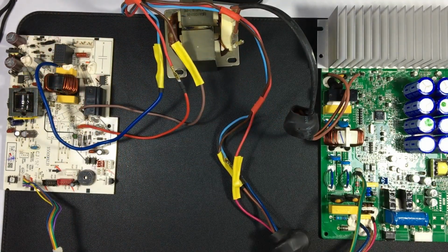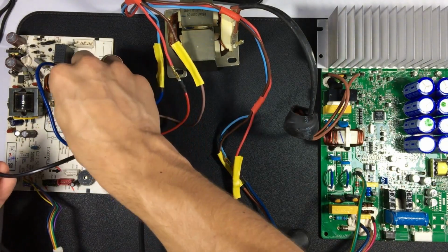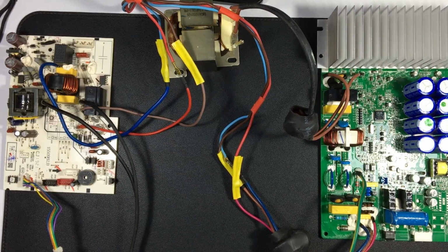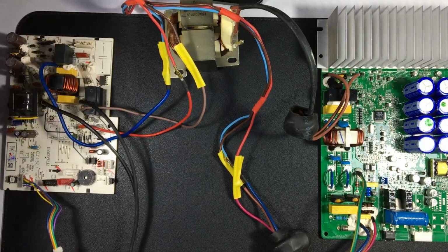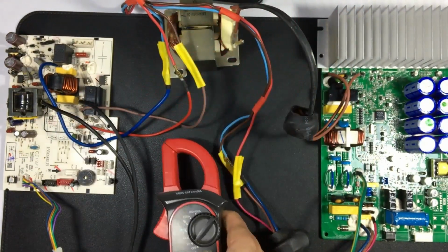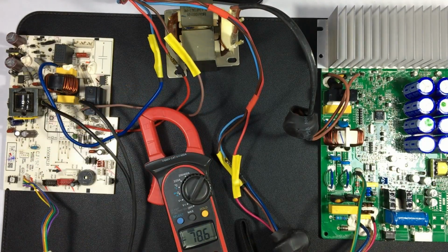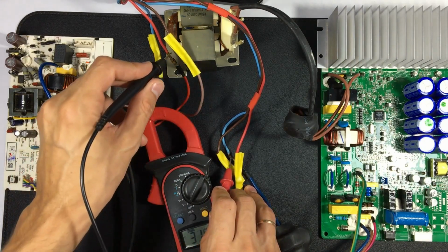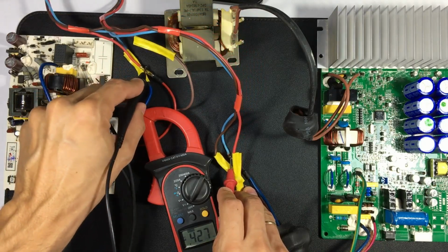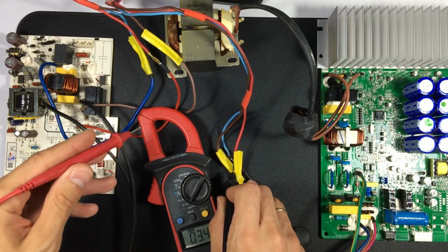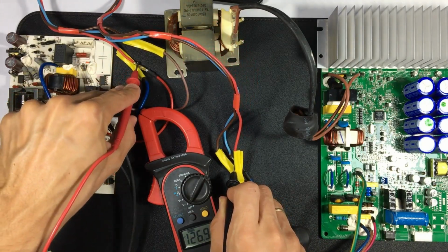The first thing you will do, when repairing or checking inverter air conditioners with a communication error, is to energize the indoor or outdoor unit, whichever is energized, and take some measurements on the communication cable. How do we do it? With a simple multimeter. We place the multimeter in direct current and measure between the N cable and the S cable, and we observe what appears on the screen. Preferably, place the black lead on N and the red lead on S, the communication cable.